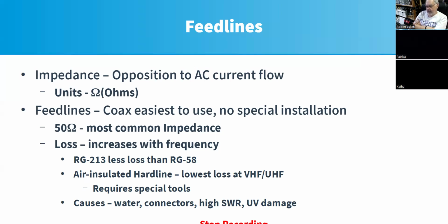In the case of what we use, if it was an infinitely long piece, it didn't matter what was on the other end, it would appear to be 50 ohms. If you try to calculate what it is, it's very complicated because it's a lot of series and parallel inductance and capacitance. Basically, you just remember it's most commonly 50 ohms impedance.